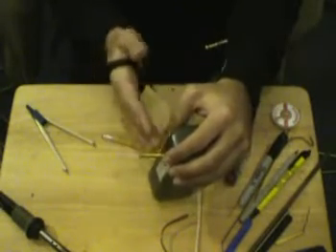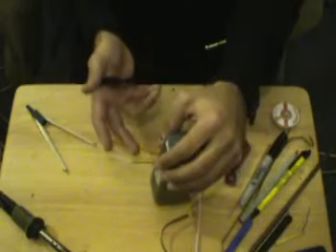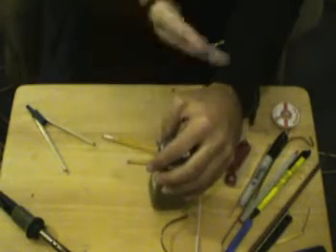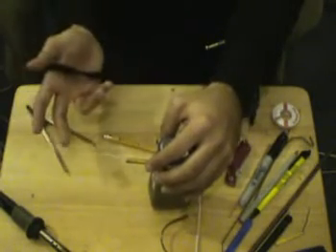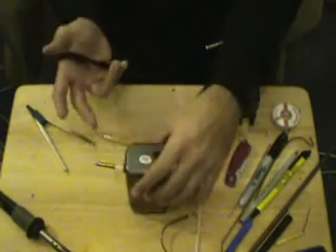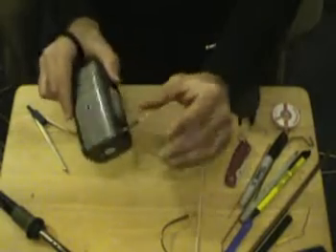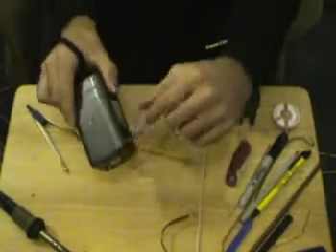On average, a full wavelength of 2.4 gigahertz is almost 5 inches. So if you have one wavelength on each side, that'd be a full wavelength dipole, but that could also change. You could also be picking up spurious frequencies across other bands. So this is usually why you keep things as specific to the frequency as possible.